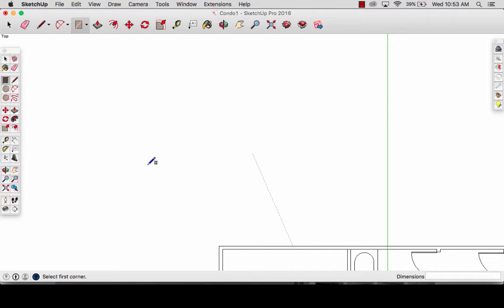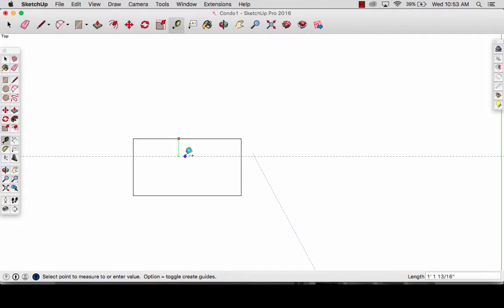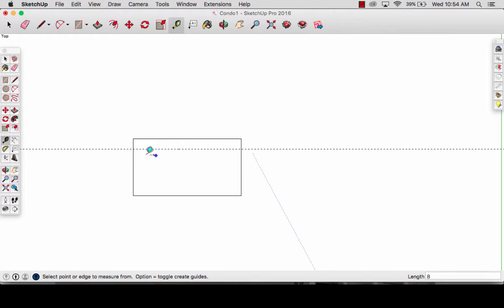I'm going to activate my rectangle tool by pressing R or this button up here. You're just going to click and release and start typing 7 feet, comma, 45 inches. So that's 7 feet by 45 inches. Okay, so that's the basic shape of my sofa, and you can go ahead and add details if you'd like, add a back to it, a little bit more than that, add some arms, however you want to illustrate a sofa to your client. Works just fine with me.